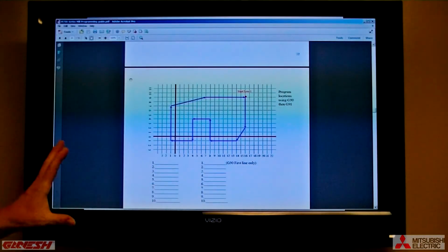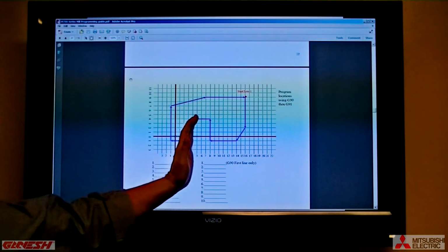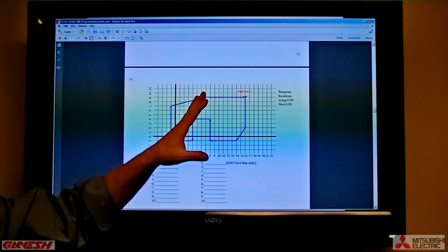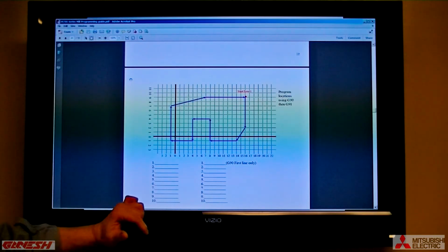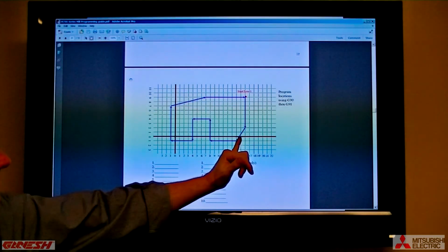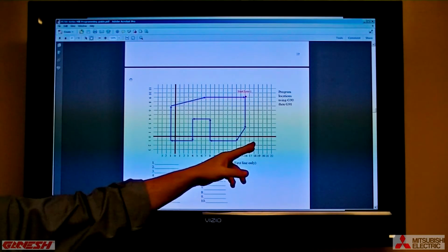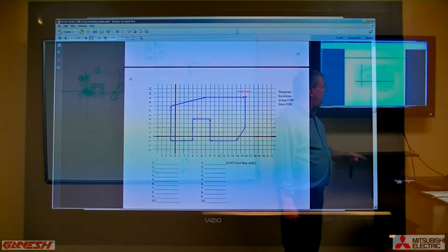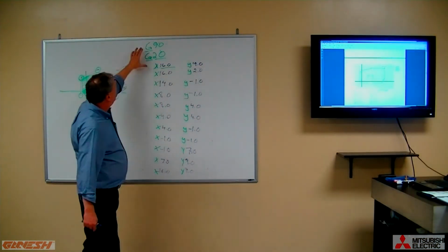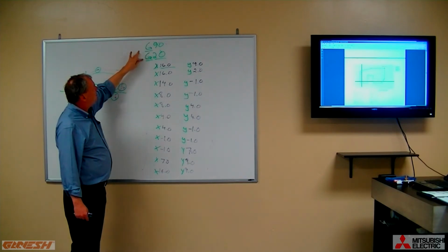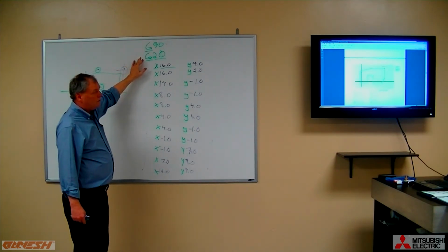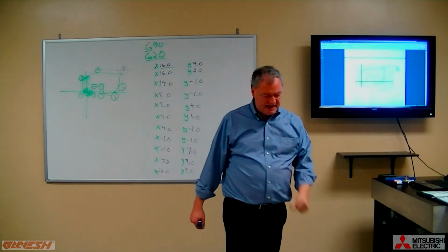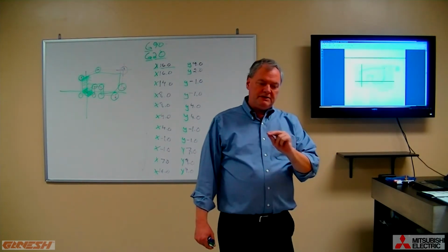So we've not only now introduced you to the Cartesian coordinate method of thinking, which is the basis of all NC programs, we've also introduced you to the concept that we now have units and we have ways that we can express numbers differently. Are they absolute numbers from an origin point? Yes. If so, conceptually we now use what's called a preparatory function to advise the control that that's what we're going to do.